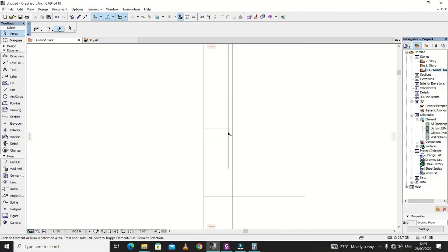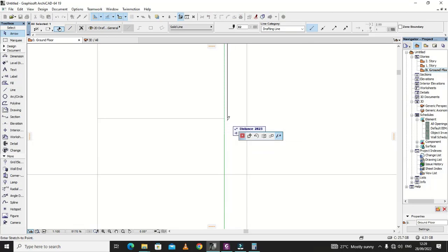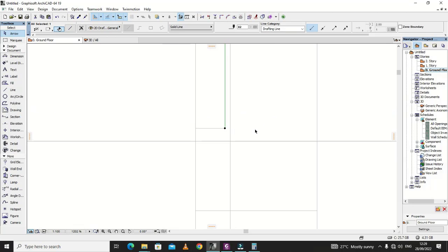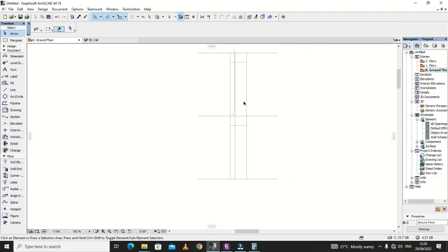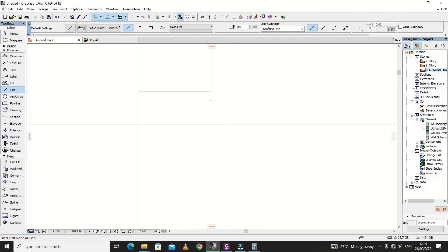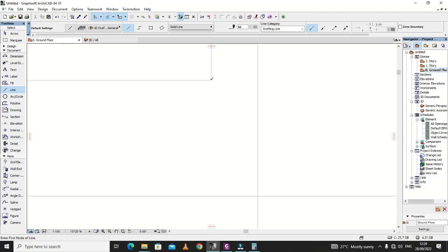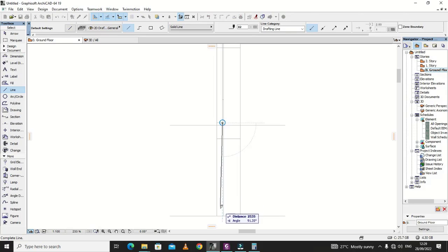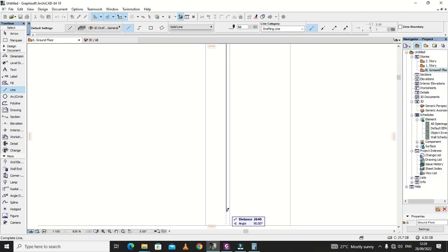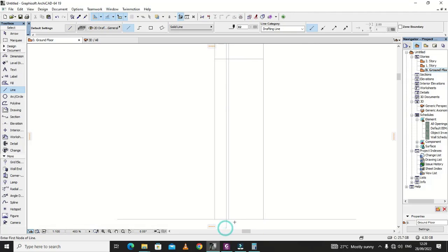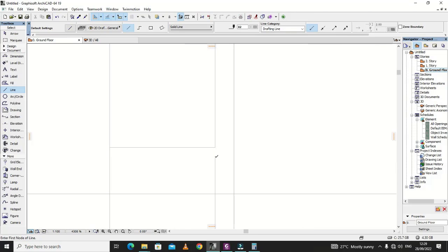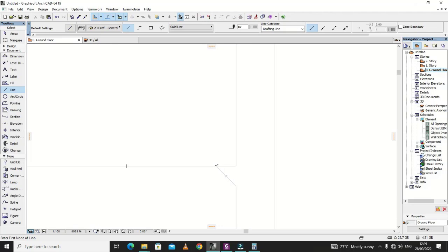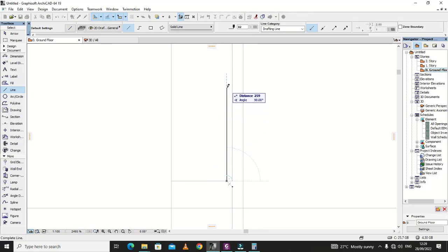So we are going to lap this bar with the one which is going to come from below there. We are going to lap this bar with the one all the way from the ground floor. Since we're going to lap it, let's say we're going to go to a distance of almost 15 from here, just an arbitrary distance. That doesn't really have to be accurate. Also this one we shall terminate at the kicker, so we shall do that later. Then just do like this, that way, and lap it from here, and then we shall go 600.